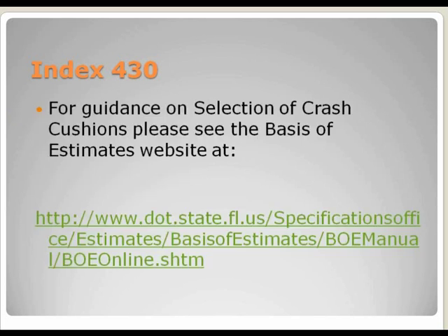And again, if you need guidance for Index 430, since it's no longer in the design standards and you need to select crash cushions, you can see the Basis of Estimates website. They've done a pretty good job of trying to outline how to actually do the selection. Is this a hot link also? Yeah, this should be a hot link. If you go to where we have the presentation stored and click on this, it should take you to it.